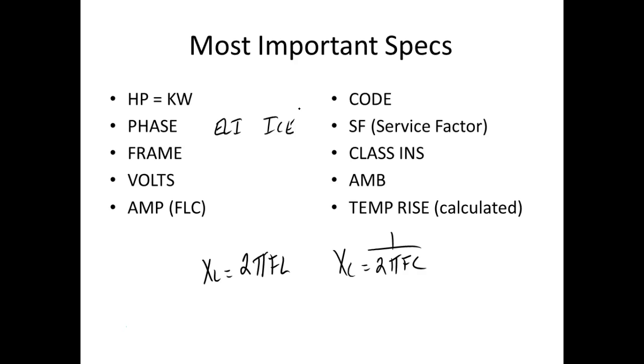And if we put them in the circuit at the same time, depending on how we arrange them, they will cancel each other out. So I've got an inductor that creates a lagging phase shift, which means the current is lagging. And I can put a capacitor in there in parallel with it, which creates a leading, and I size them right for 60 hertz. They will literally cancel each other out. So the new motors,